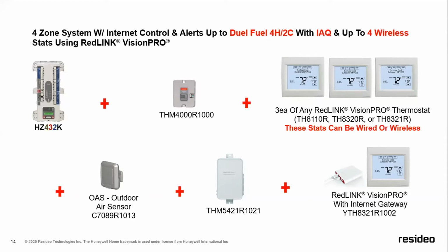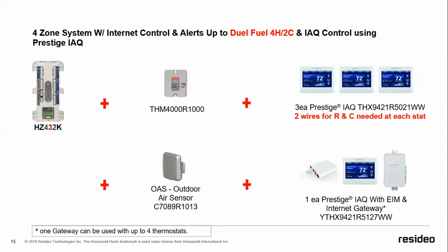So now that particular device is going to be hardwired probably into zone 1. You make that particular choice, and it essentially becomes the sub base for one of the 4 thermostats that you see on the screen. And so all the thermostats are learning what the outdoor temperature is from 1 outdoor air sensor. Okay, if you'll go to the next slide, please.